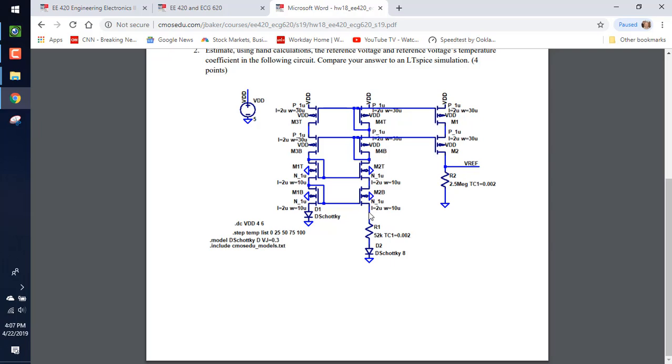What's this voltage right here? VD1. What's this voltage right here? VD2. So what's the current flowing? Minus VD1 minus VD2 over R1. So if I asked what is the voltage right here? That current times R1 plus VD2. So everybody understands that, right?